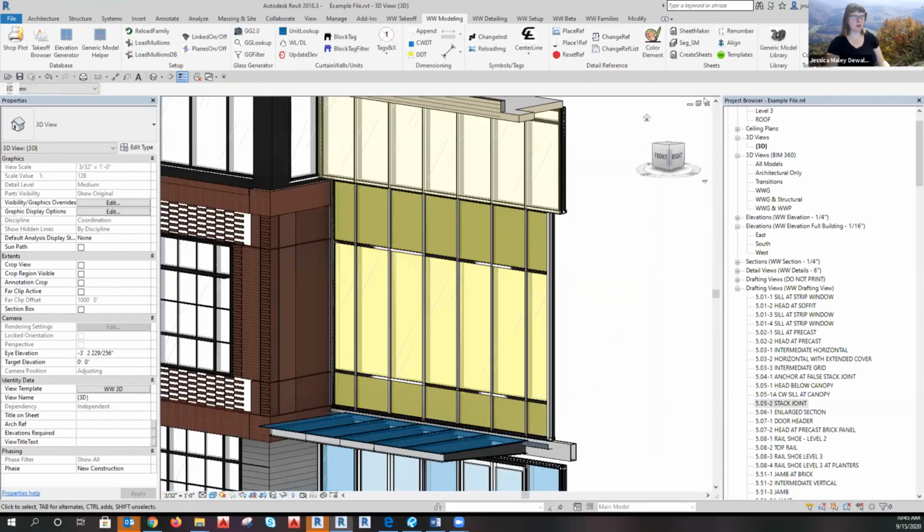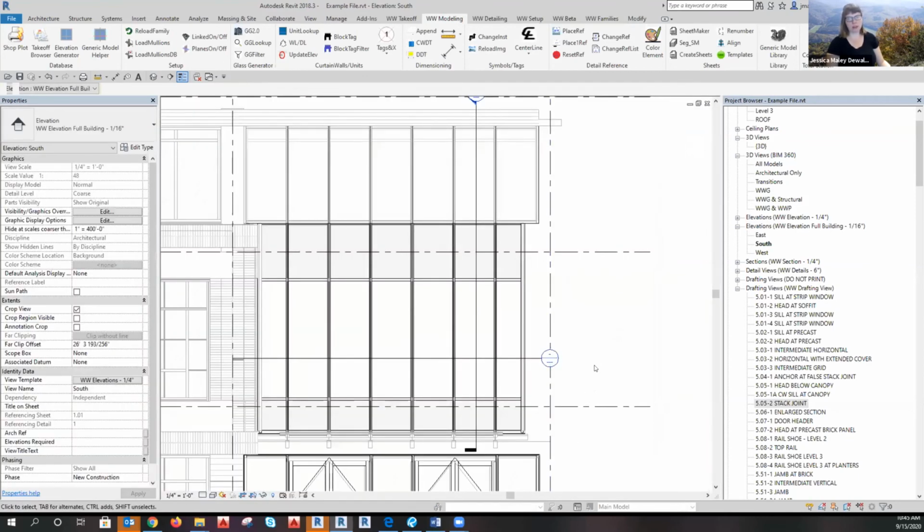All right, thanks. Okay, so now we've got the glass, and again, once you generate it, especially your first couple of elevations, you're going to want to do a bunch of live cuts, measure everything, and make sure it's correct, because that's your chance to double check the data. But we're not going to go through that right now because we don't have time. So we're just going to assume it's all correct.